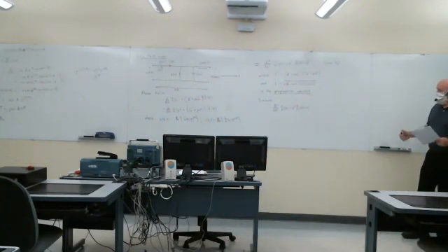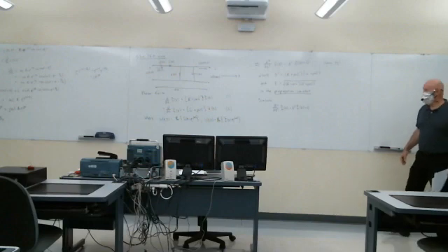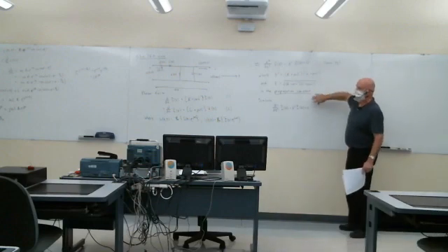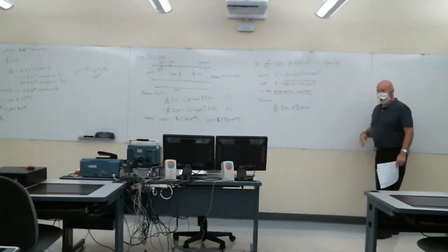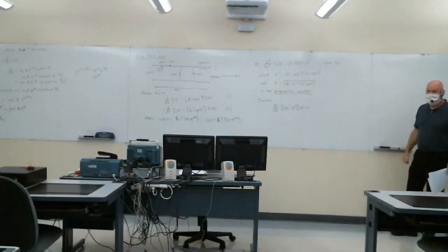So the solution forms for the voltage and current will have to be the same, except they can differ by a complex constant. I can multiply either one of these by a complex constant, and it would still be a solution to the equation. So my I and V phasors just differ by a multiplicative complex constant.